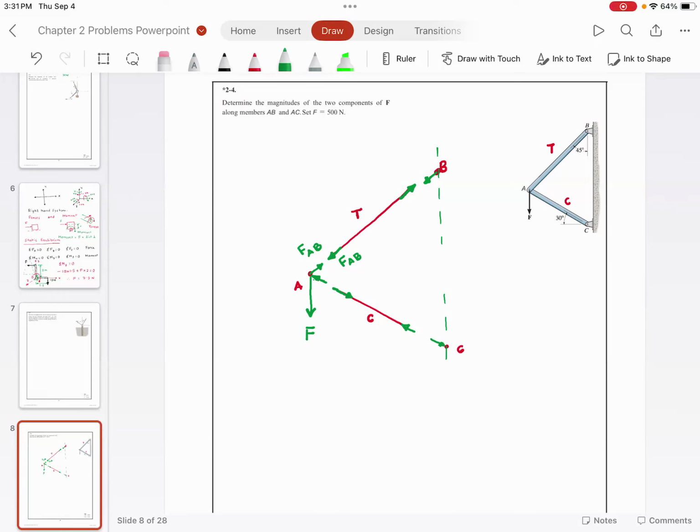Which means right now I have freed the body. If I were to combine the body together, if I were to add everything, you see that I just get that truss over here. Agree with me? If you look at that truss, it's extremely important. The only thing on that truss is the external force F. But because of the external force F, internal forces FAB and FBC are generated. FBC, FBC, FAB and FAB.